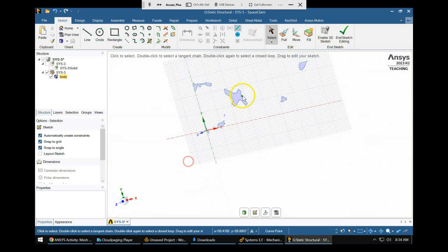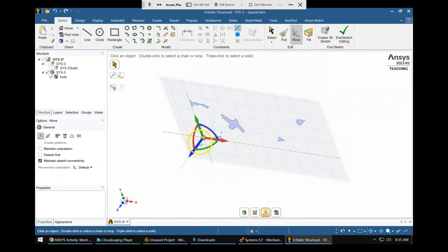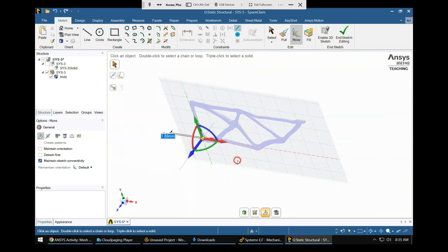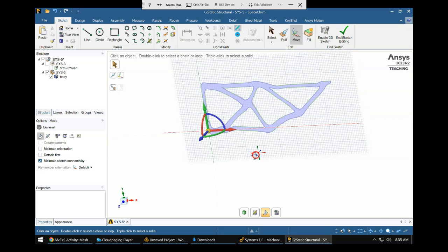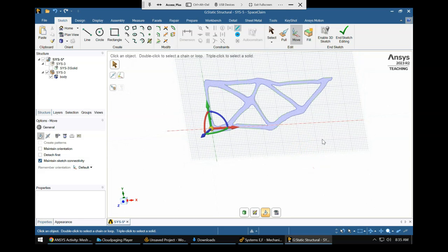Right now it's only intersecting part of the model, and so I don't get that clean geometry to extrude. But I can move that plane. If I click the move, and that move triad comes up, and I drag the axis, I can find a spot where I get a good cross section, and I could extrude that. So that is still an option if you wanted that uniform thickness shape extruded. We're not going to do that for this one, but just showing how you could do that.